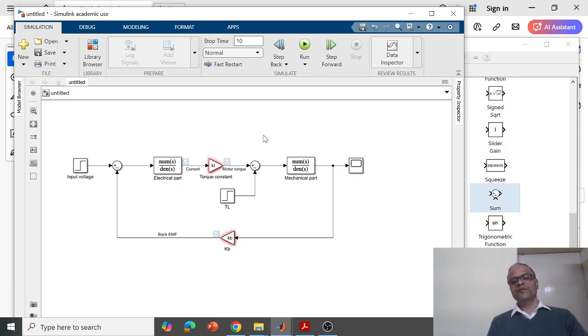So what Simulink is going to do is, by making this model, Simulink would be able to internally find a transfer function and a model of this whole combined block, closed loop system, and then it essentially numerically solves this system. For example, if it makes a state space model of this, it will numerically solve that state space model using a numerical method to solve differential equations, and then it gives the output. So let us click this run button here, which essentially is for simulating the model.